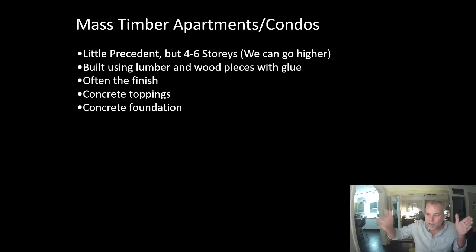So we can't have a whole series of beams close together. That doesn't meet the intent of mass timber. What we need is big flat surfaces. The reason we need big flat surfaces is that wood will self-extinguish on a big flat surface. Wood only burns in the presence of an external fuel source if you have big flat surfaces. If you have a bunch of joists together, it creates a re-radiating zone and then it will burn, but a big flat surface won't. And anybody who's tried to light a campfire knows that that's true.